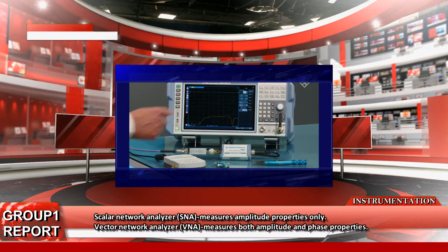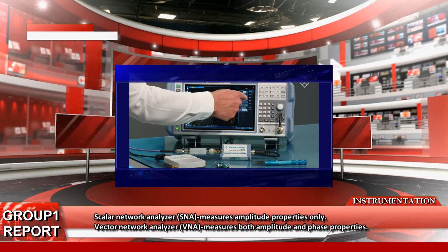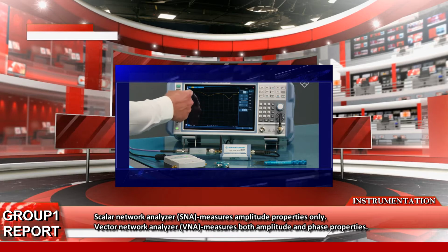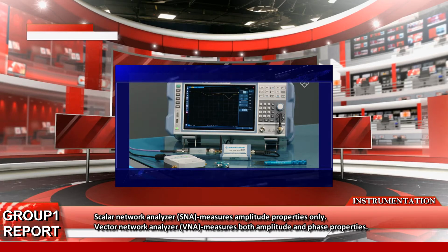A VNA is a form of radio frequency network analyzer widely used for RF, or radio frequency, design applications. A VNA may also be called a gain phase meter or an automatic network analyzer. An SNA is functionally identical to a spectrum analyzer in combination with a tracking generator.